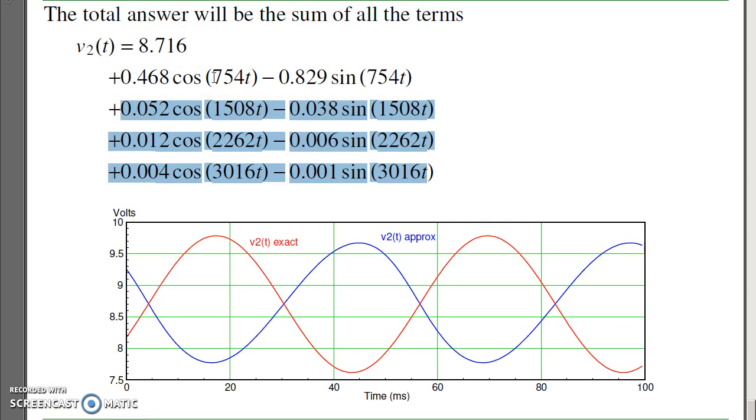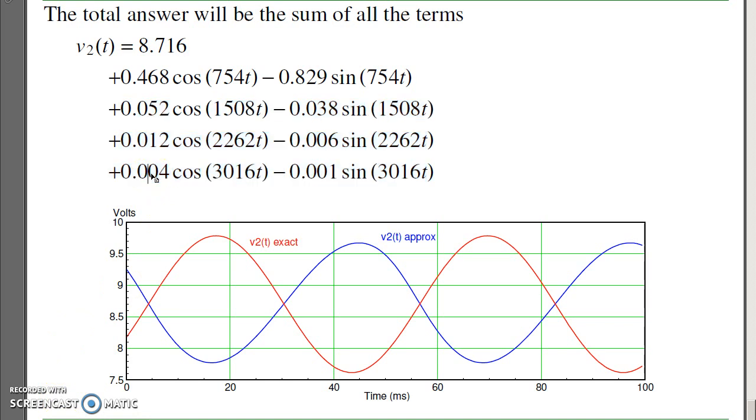So likewise, the Fourier series in theory says I have to go out to infinity. In practice, all I need are two terms typically, the DC term and the first harmonic. That's Fourier transforms. You'll see more of this when you take 343 signals and systems. We're covering that now because once you have superposition, you really have Fourier transforms.